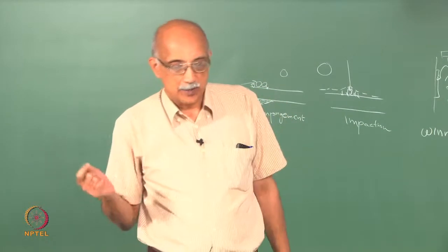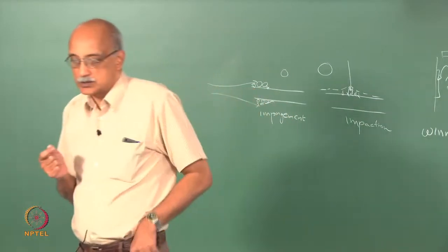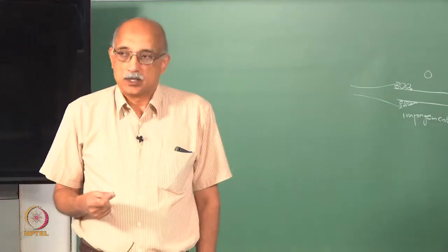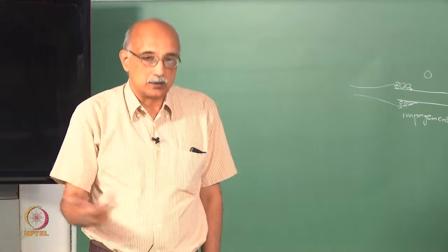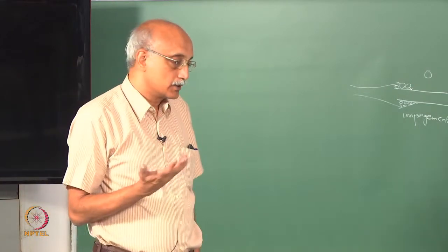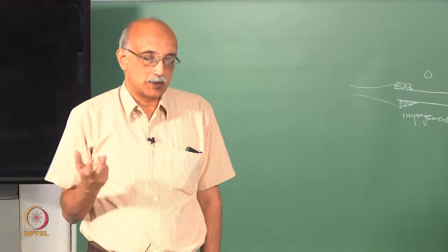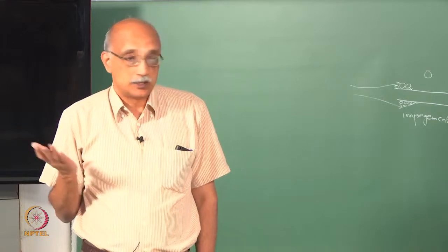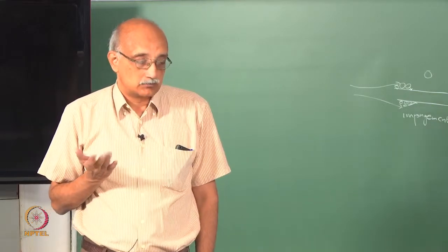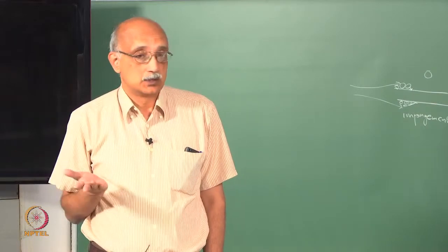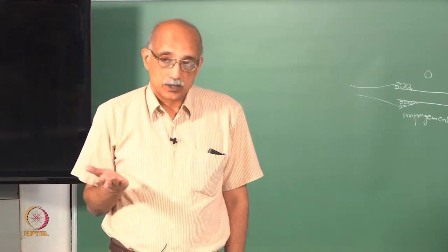So, as soon as your sample contains particles that are smaller than 200 microns, you have to start using magnification. Magnifying lens, optical magnification is the simplest alternative, and it used to be that with an optical magnifier you could only go up to about 100x magnification. Now there are even optical microscopes that can go up to 10,000x magnification.